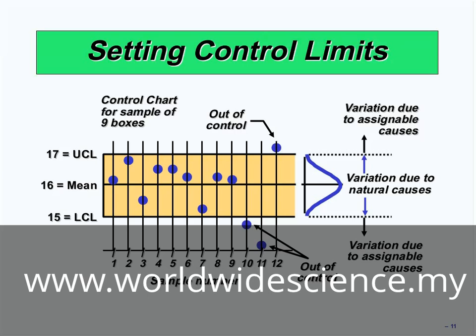When you draw the chart, you should identify UCL and LCL in the chart, go to the table again and specify each X bar in the graph, and see whether all of the X bars are located in the range or not. If only one is out of this chart, you should see that the process is not under control and there is something wrong.